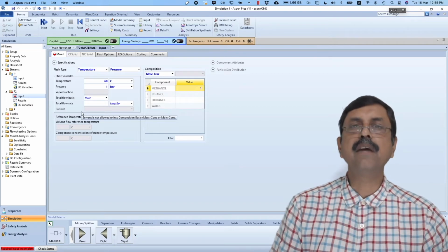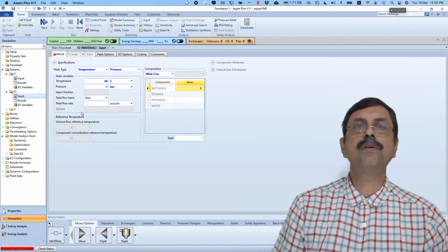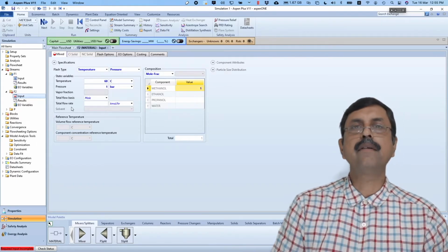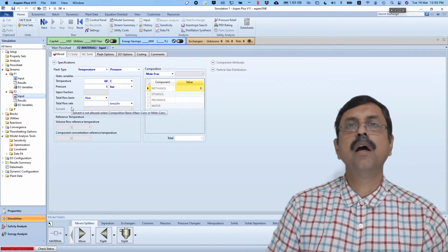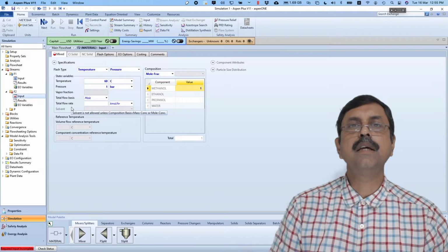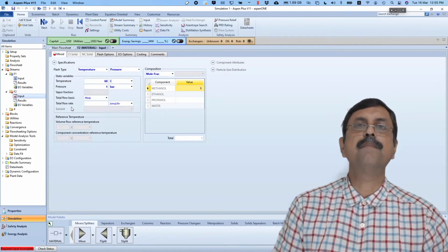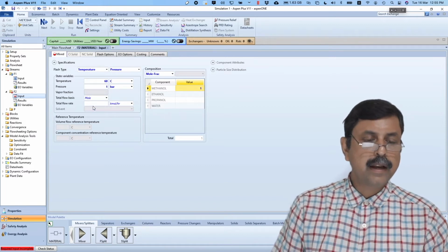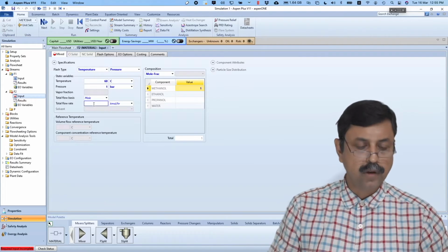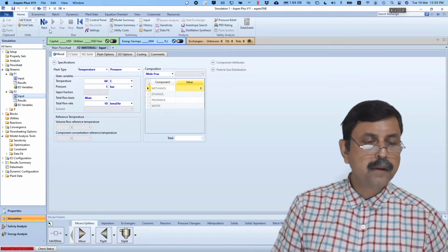So we have to give some information to it. But our target is to find out for which value of this flow rate we will have the output or product quality to be 53% methanol. That we will see later, but for the time being we have to give some data. Let us give a value of say 10 kilomoles per hour to begin with. Press next.